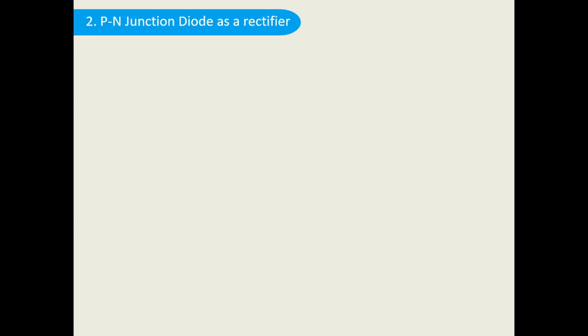That's why the efficiency of the half wave rectifier was less, we can say it is half, because of the two cycles, positive and negative, we were getting the output only in one cycle, that is the positive half cycle, while the output was zero in the negative half cycle. So for one complete cycle we were getting only half cycle in the output side. This decreases the efficiency of the half wave rectifier. How it is overcome in the full wave rectifier we are going to learn now.